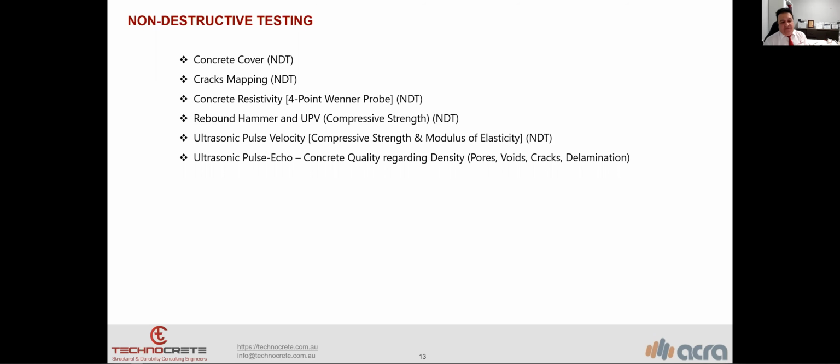For example, if we have voids of 2 or 3 millimeters in diameter in the concrete, then they are based on construction errors, maybe lack of proper compaction. We can understand all of them when we assess the concrete.